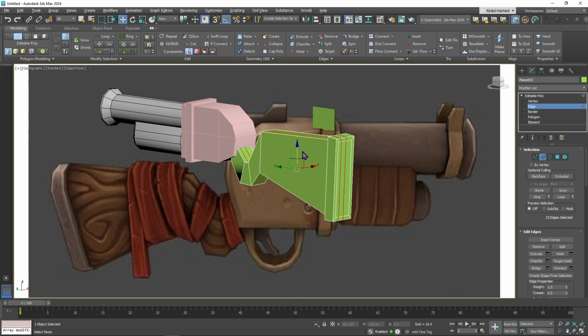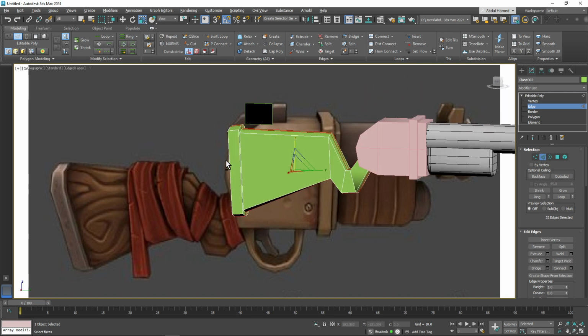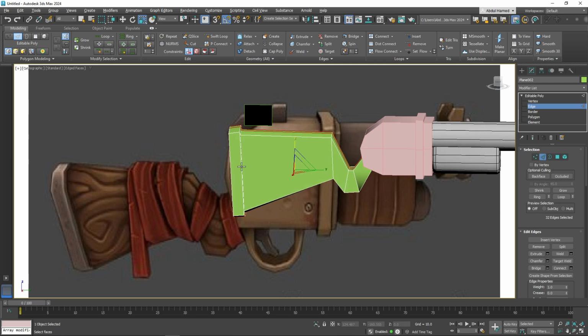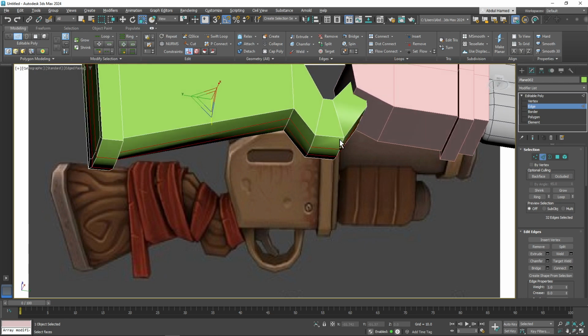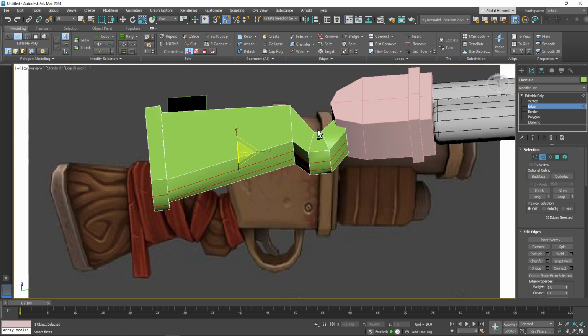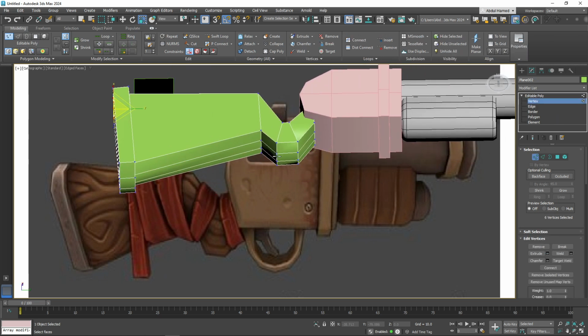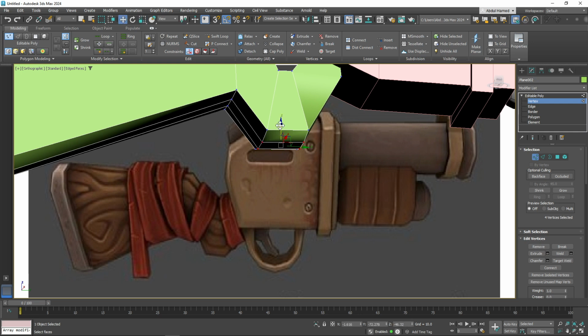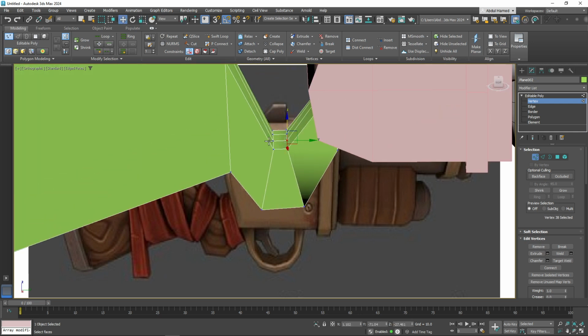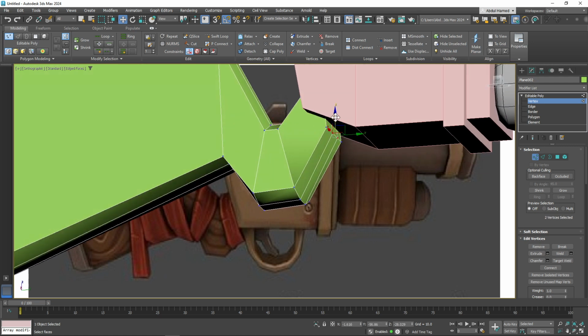So what we can do is we scale on the z-axis. So we can see this is not being affected here, so we can do it manually. But the overall is looking much better. So let's select the vertices and let's fix those ones. W and then push it out. And these two, push it up. And these two, push it down.